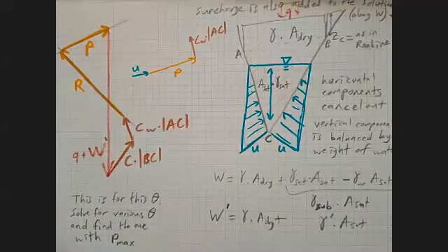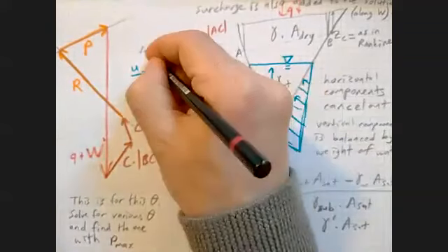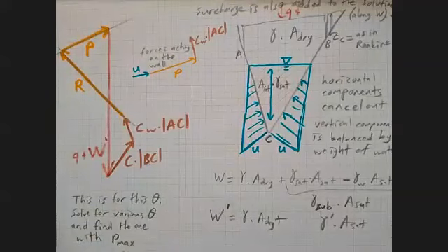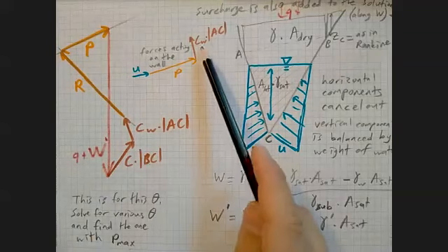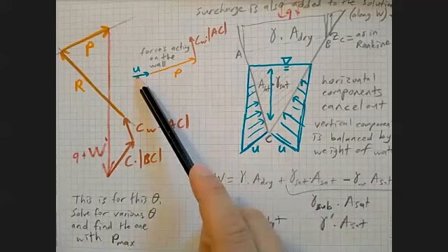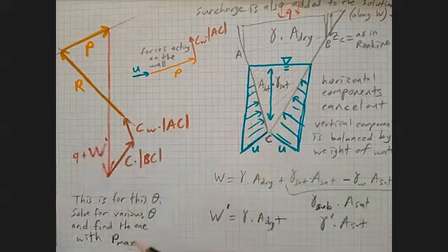So this will be forces acting on the wall. But in this consideration, in this finding maximum P, maximum force on the wall, this cohesion with the wall or adhesion with the wall is constant. The water surface is constant, or not constant, but they are independent from theta. The only thing that is dependent on theta is P. So it is enough to just maximize P.